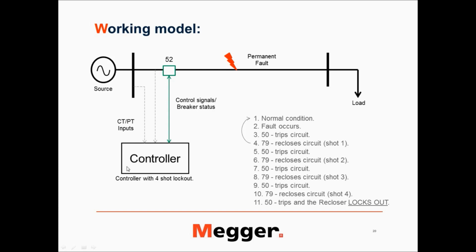And that's easy because at the circuit breaker, the CT inputs are on all three phases. So the controller is going to see an increased amount of current on the specific phases where the fault occurred. The only thing is the controller should have 3 trip signals or 3 outputs assigned specifically for A phase, B phase, and C phase, and that should open the circuit breaker or the single pole autoreclose just on those specific phases. It is not opening all 3 phases at the same time.